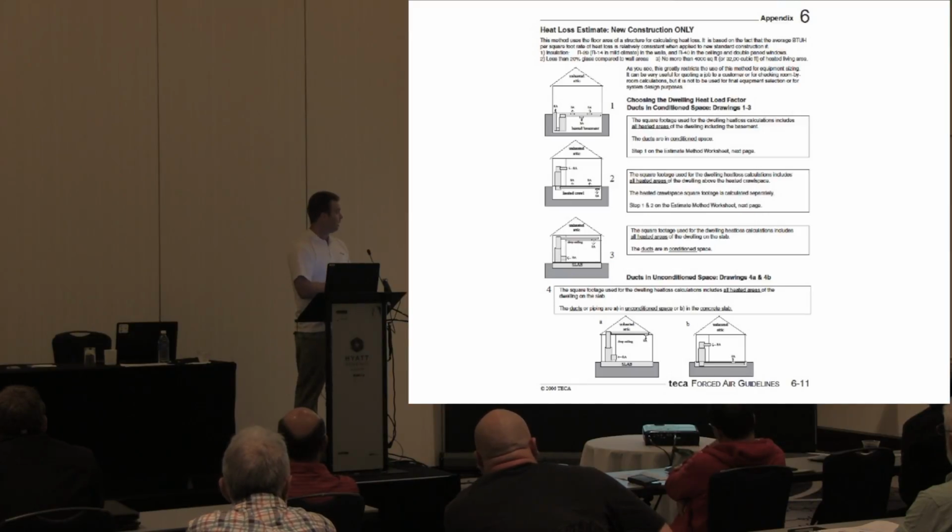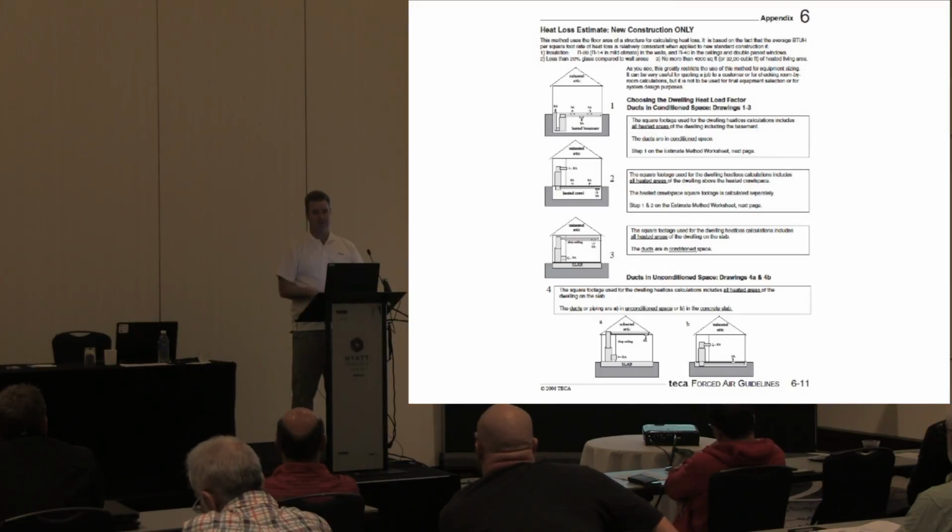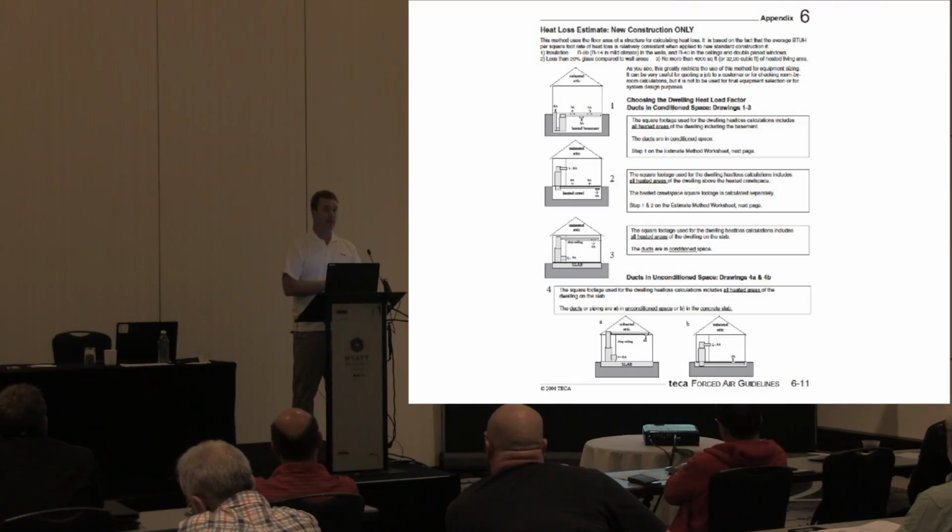So, if you did all that, that's the most accurate way. That's the way I do it when I do a quote. I get the wall square footage, the window square footage, the door square footage for that matter, wall, ceiling, floors, add them all in off a set of plans, it spits out a number at the bottom, and I'm done. And then you're able to get some kind of idea. When I use that number compared to when I do a room by room, it's within 10%, as long as I take the right information off the plan. As long as my information is accurate off the plan.